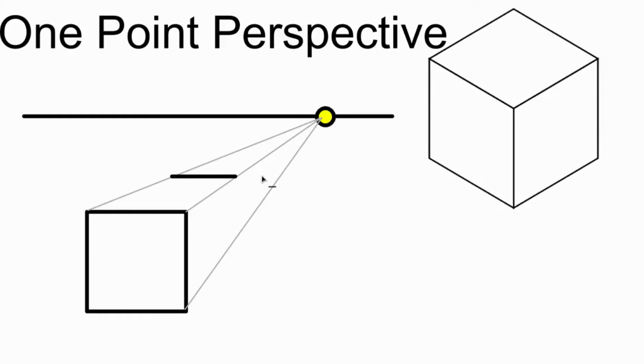So I drew a horizontal line in the back, which represents my line on my top view, back there. And then that point connects down, and I want to drop a vertical line from that. So I'm going to take my point and drop a vertical line down. Now at this point, all I need to do is go back in and connect my lines.